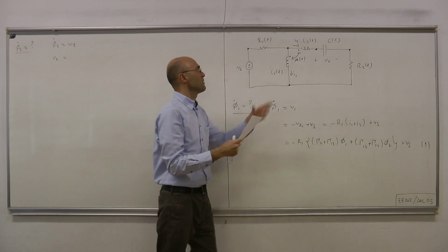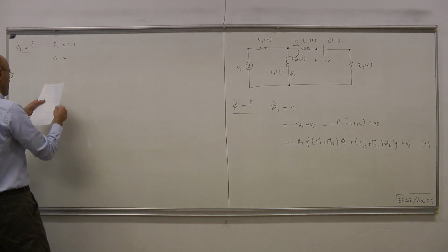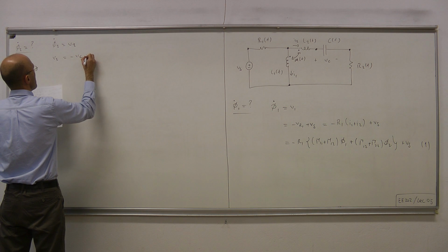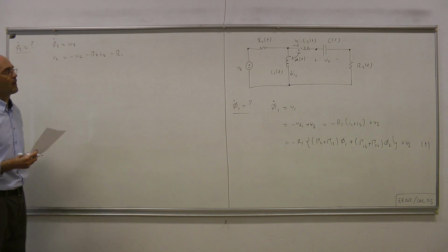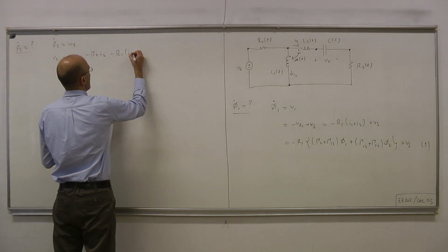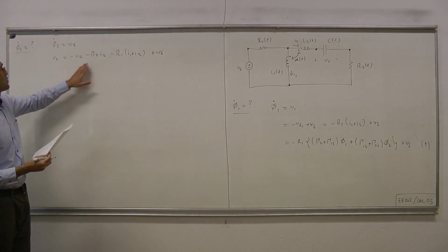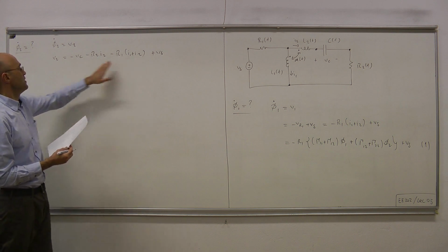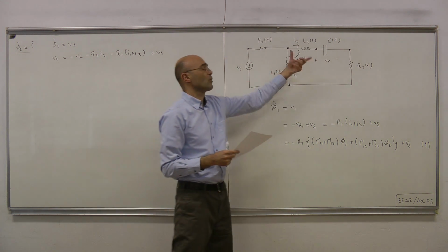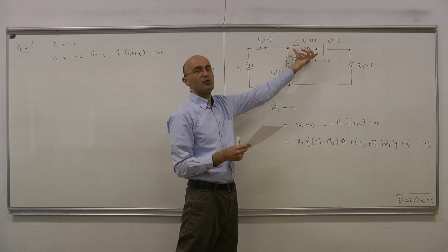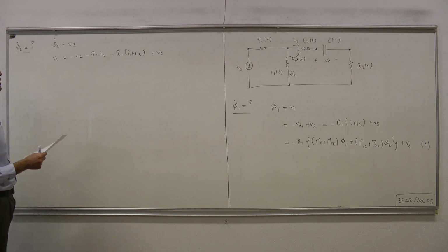If you write that equation and then pull V2 to the left hand side, what you obtain is the following: minus Vc minus R2 I2 minus VR1, which is R1 times (I1 plus I2), and finally plus Vs. Okay, so this is VR2, this is VR1, Vc, Vs. So basically, we wrote KVL on the outer mesh for the fundamental loop, and then from that KVL equation, we obtained V2, the voltage of the second coil.